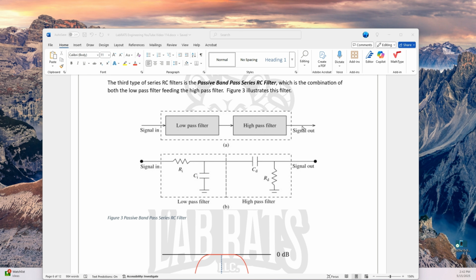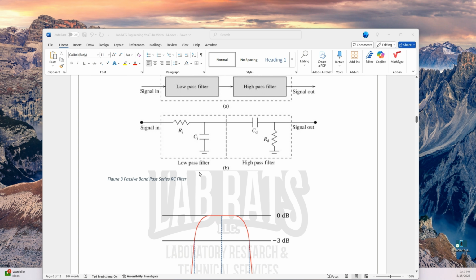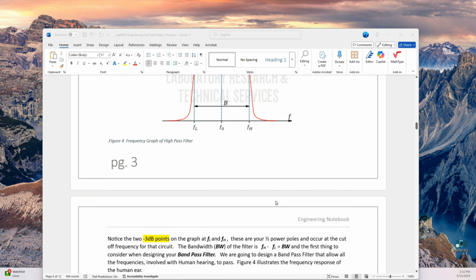And those thus are the upper and lower boundaries of the human ear, and that's what we're designing a bandpass filter towards. So our first one, we'll have this cutting off. The FC of this circuit will be at 20 kHz, and the FC of this one will be at 20 hertz and above, producing this plot right here. That's our bandwidth plot.